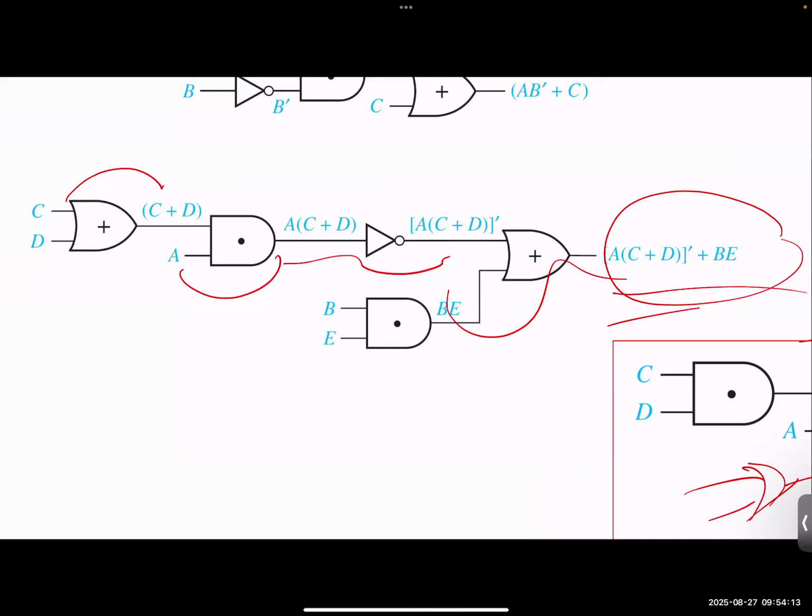So creating the truth table is the first thing that a reverse engineer will try to do. And how do they do it? Imagine you throw a Core i7 processor somewhere and somebody gets hold of it. They smuggle it to a company that's trying to steal the secret that Intel spent years developing. They'll probe it with their probe station, provide inputs, take the output. It will take months because there are so many combinations, and they will create a truth table. They'll reverse engineer. Once you get the function, you don't even have to go through and recognize the circuits individually. You can generate the function and design the circuit backwards.